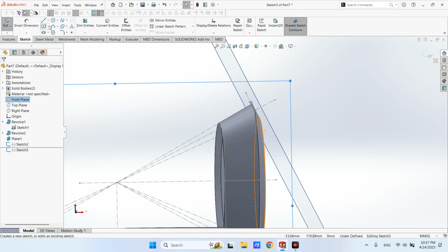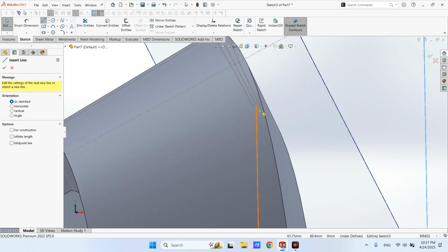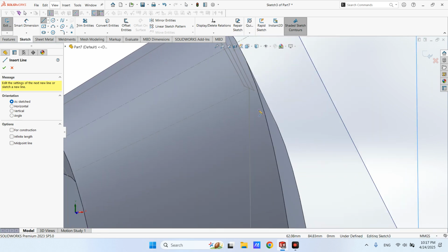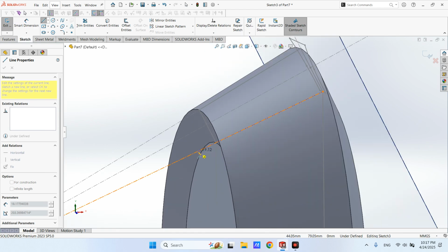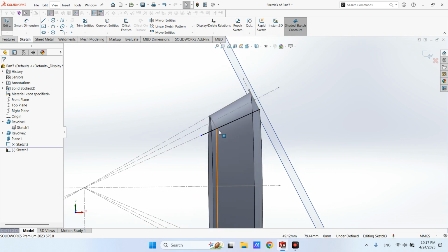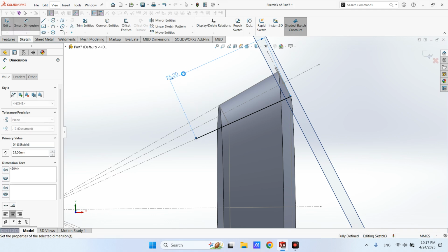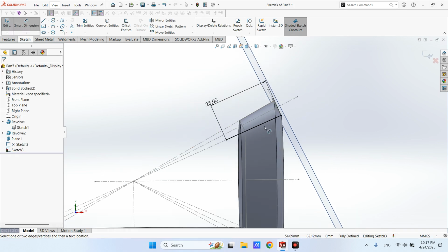My path is this line, as you can see, from the middle of the sketch and in the bottom center line of the teeth. Somehow like this, and this must be out of my model, so I add a dimension to this. For example, I add 25 so that I will make sure that it gets out of my model.